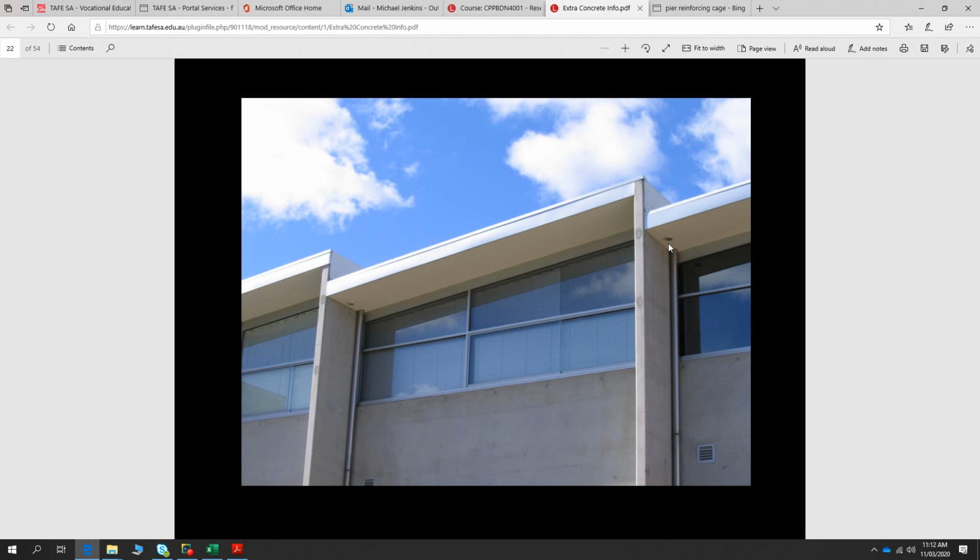A less neat way of doing it is to have a steel angle in here. You fix there and you fix there. Much simpler and much easier to reinstate, but means if it's a warehouse, you don't want to have forklifts and things like that operating near that. You don't really want that sort of thing in a residence either. So that's the quick, easy, cheap way of doing it.